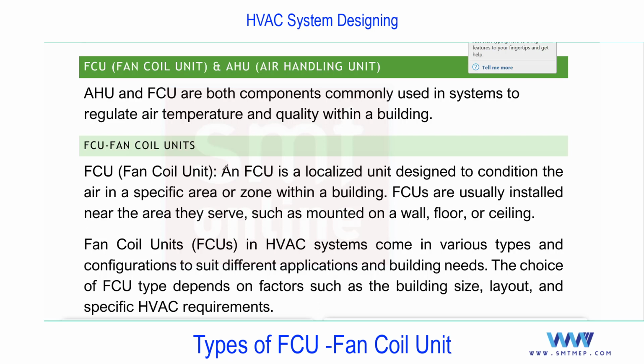Both can be used for a cooling system or for a heating system, depending on the type of coil or the type of system it is connected to. If that FCU is connected to the chiller, chiller means you can expect cooling. If it is connected to the boiler, you can expect heating. Or if it is connected to a VRF system, as we discussed in the last session, if it is a heat pump, you can expect cooling or heating as per the requirement, any one at a time, or heat recovery simultaneously. So this is common. First, let me complete this FCU.